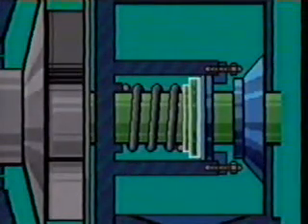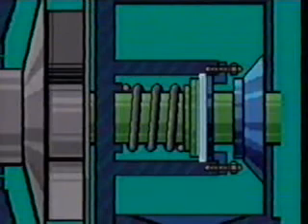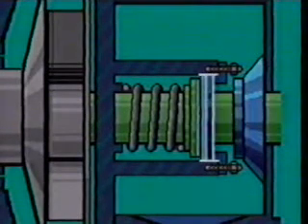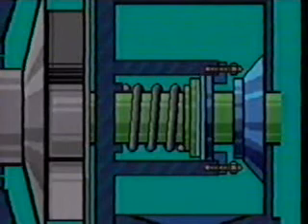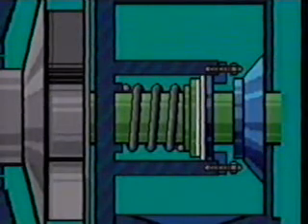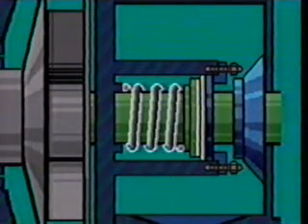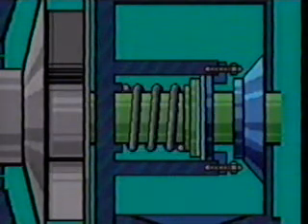Rotating parts are attached to the shaft. Stationary parts are secured to the seal plate. The seal plate is bolted directly to the casing. The highly polished sealing faces of the rotating and stationary parts are held in contact by one or more springs. In this manner, a seal is made to prevent leakage. That's the typical structure for all mechanical seals. Let's go on to bearings.